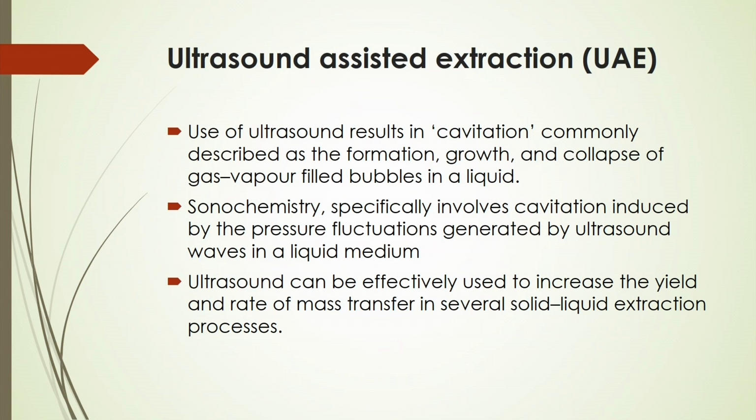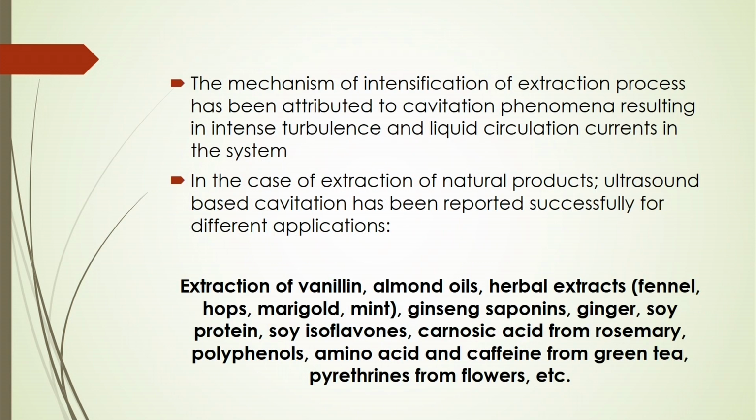In that case, ultrasound involves cavitation induced by the pressure fluctuations generated by ultrasound waves in a liquid medium, and ultrasound can be effectively used to increase the yield and rate of mass transfer in several solid-liquid extraction processes. The mechanism of intensification of the extraction process in this case is basically attributed to the cavitation phenomena that results in